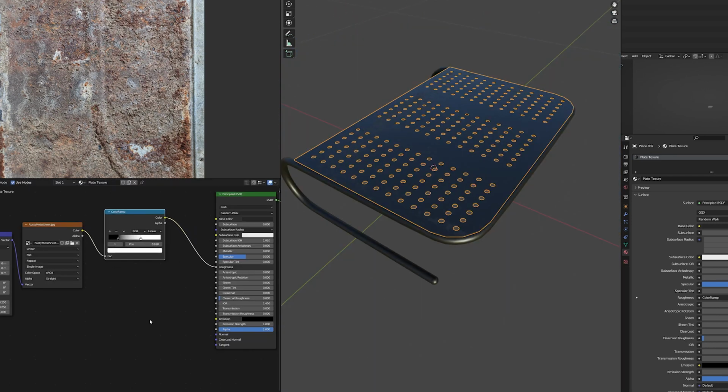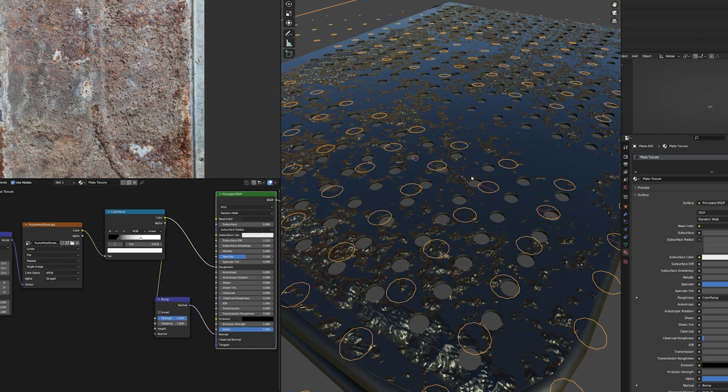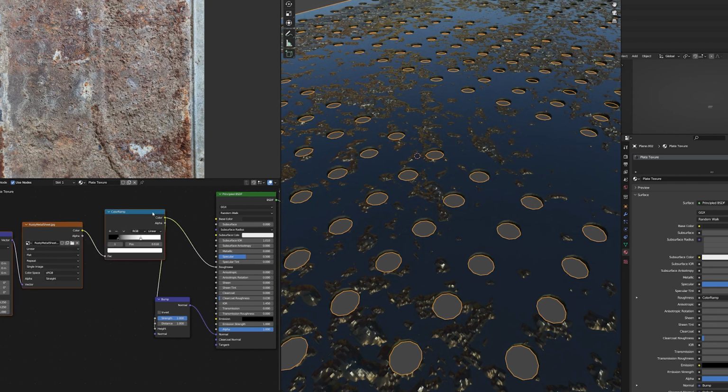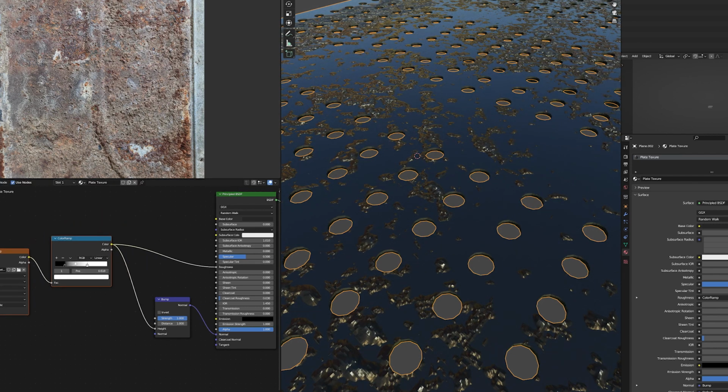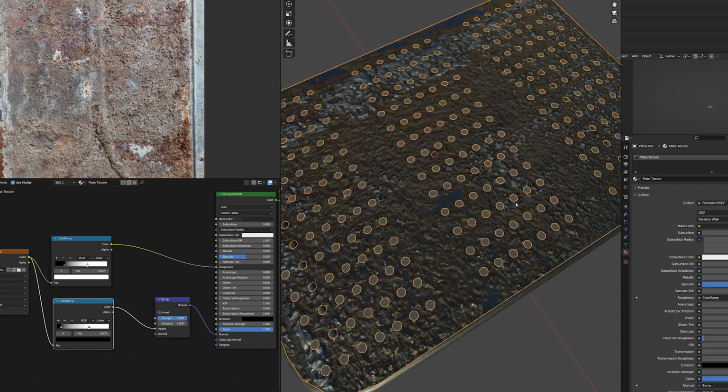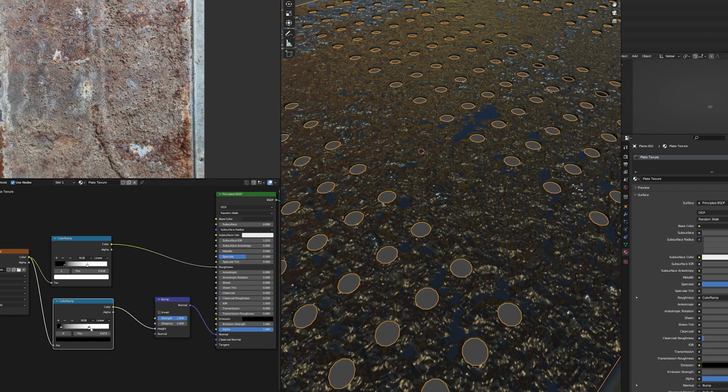I'm also going to do this trick where I open up a bump node. So if you take your photo from the color ramp and plug it into the, what is it, the height of the bump node, and then plug that into the normal, it automatically gives it this really gross bump. It's a little aggressive, but you get the idea here. Probably gonna do it separate. Ugh. Looks like it's just dipped in acid. Jesus Christ. All right, let's smooth that out a bit.